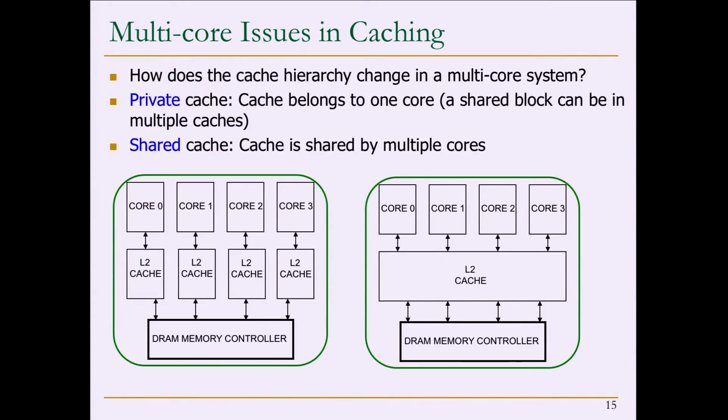That was a foreshadowing of the cache coherence problem. But that's important to discuss because it affects the design decisions over here as well. And it affects a lot of other things, which we may or may not discuss because there's not enough time. So there's one issue in caching in multi-core. Are the caches private or are the caches shared? This is true also for multiprocessors. If you have a single processor, another processor, and these are in different chips, you can again have the same problem. But in that case, private caches may make more sense on the chip, right?